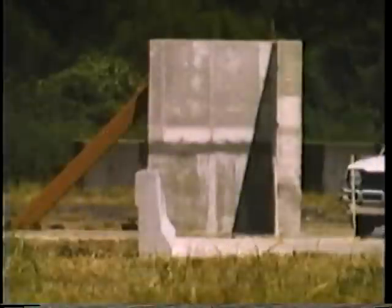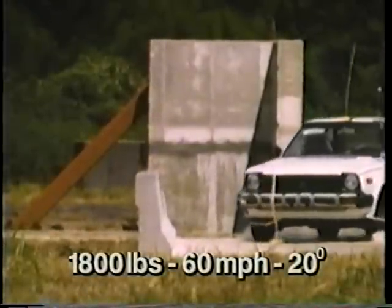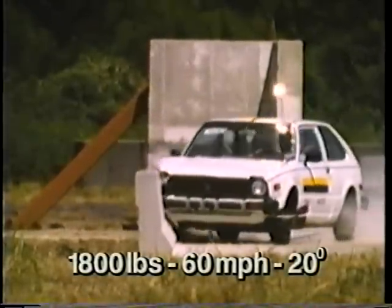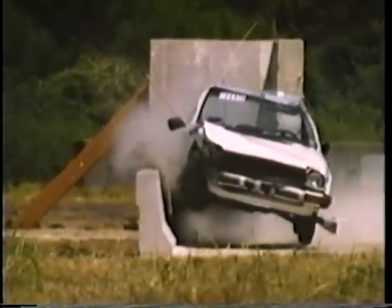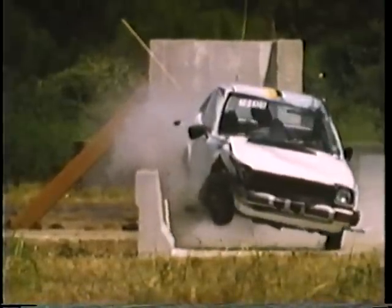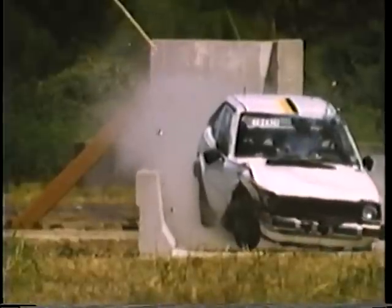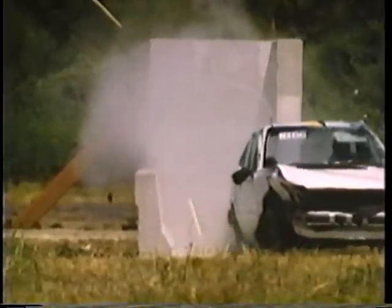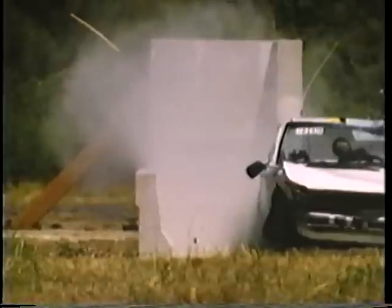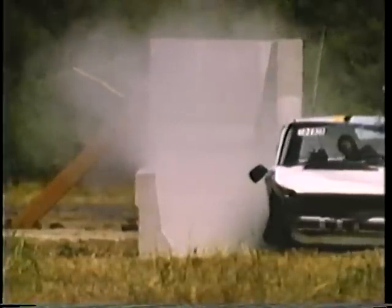Like the New Jersey shape, the F-shaped barrier dissipates energy by lifting the vehicle up off the ground and by crushing sheet metal. The occupant responses in this small car test were somewhat larger than in the tests of the New Jersey shape, although they were still below allowable limits. The vehicle trajectory, however, was much better, minimizing the possibility of a second collision or a rollover.